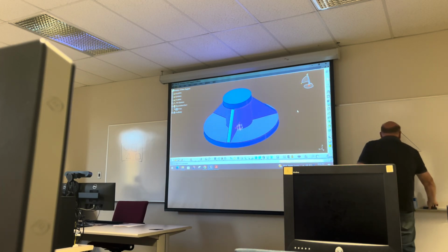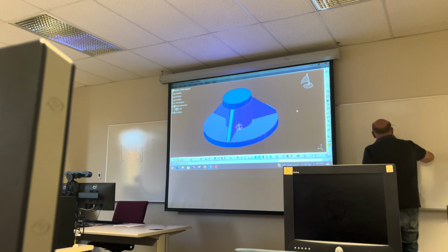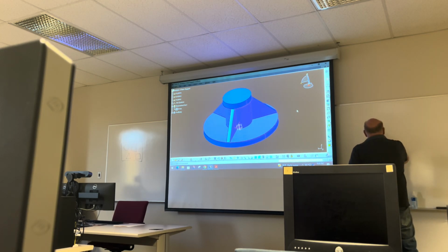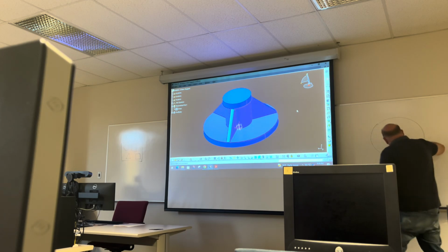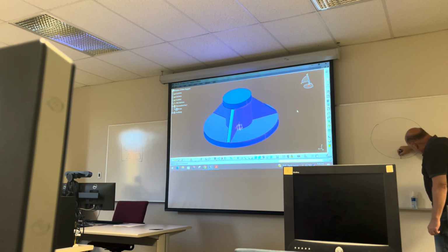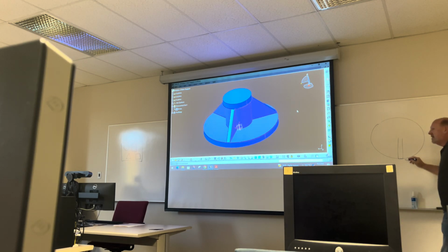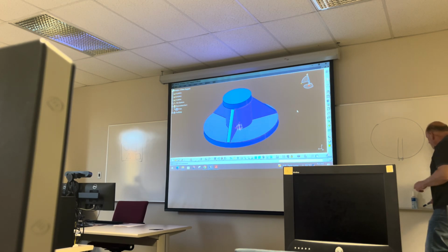So what I'm saying is, if you do a sketch like this to do those as pads, when you look at it in the plan view, that little piece that you put in there, when you push it in both directions, is going to overhang the solid. So then when you go in to put your fillet in, it's going to say, well, you've got a gap here. What's going on? I can't put a fillet in there. So I want to show you.